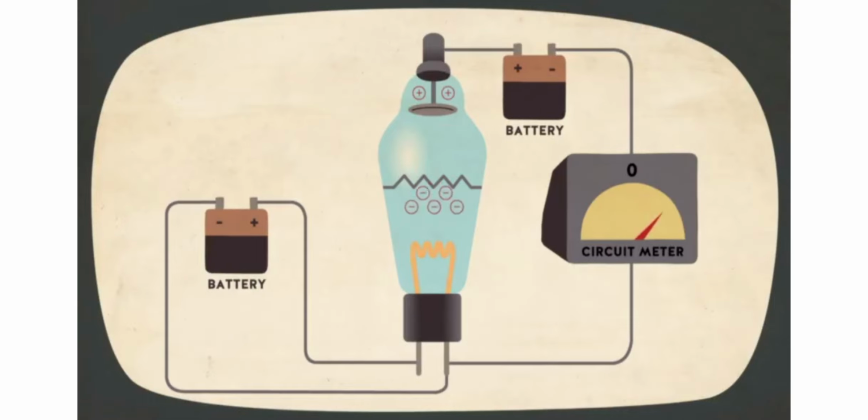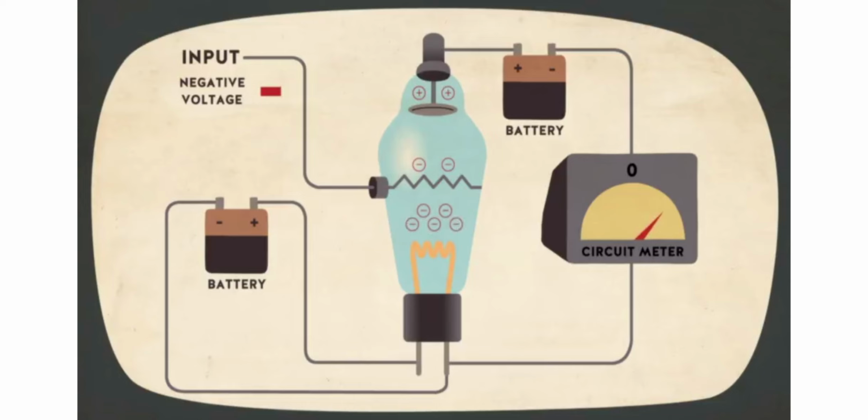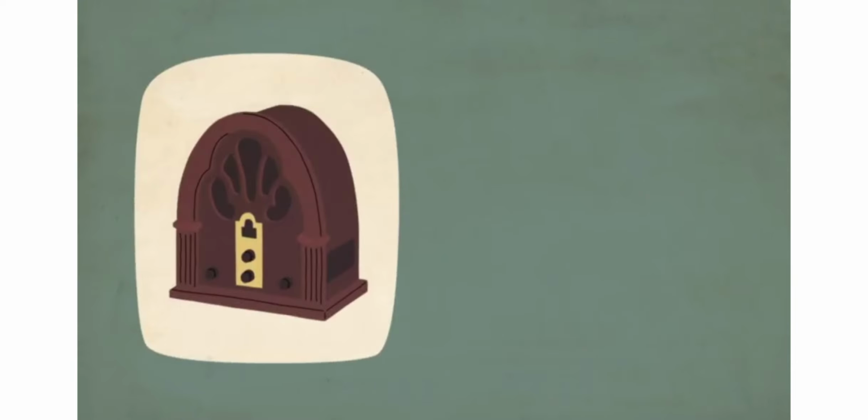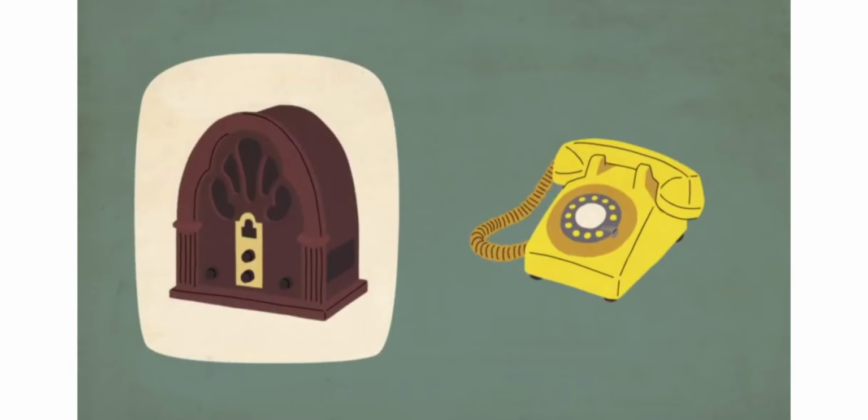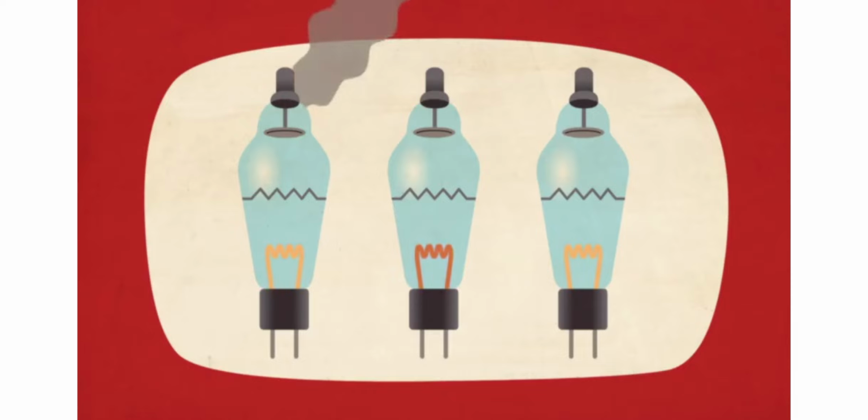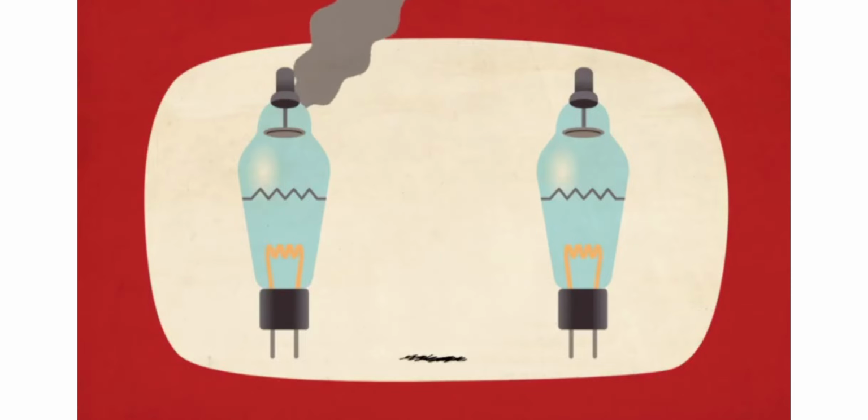This is a wire screen between the cathode and anode through which electrons could pass. Varying its voltage makes it either repel or attract the electrons emitted by the cathode, thus enabling fast current switching. The ability to amplify signals also made the triode crucial for radio and long-distance communication. But despite these advancements, vacuum tubes were unreliable and bulky.